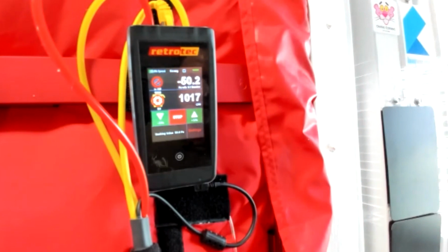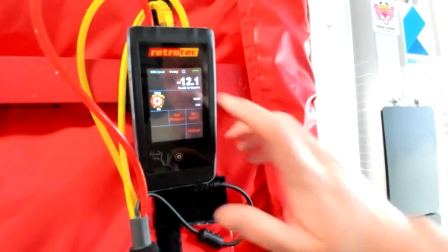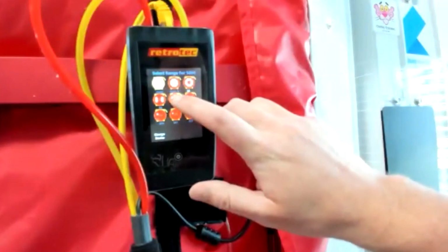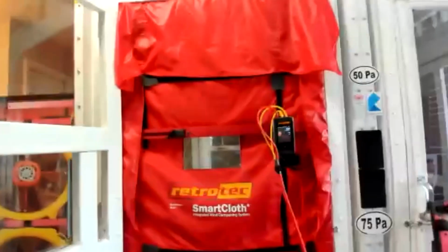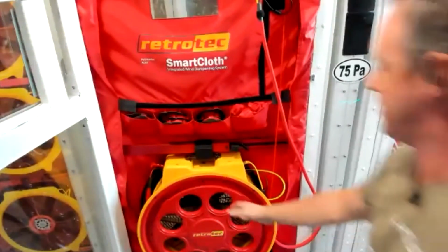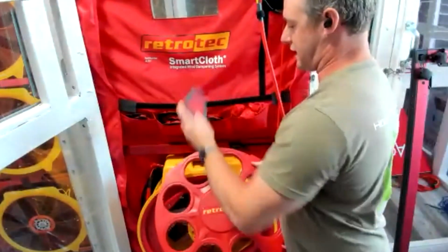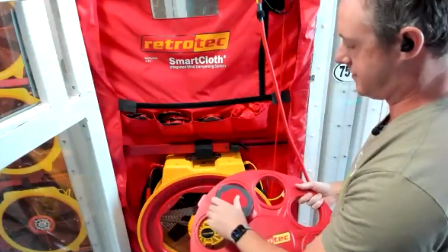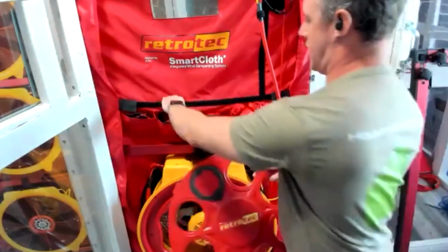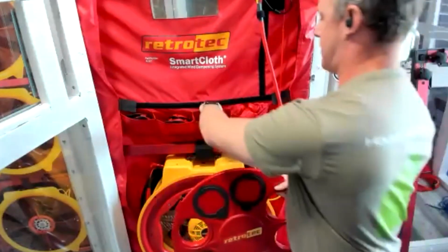Now, to demonstrate what would happen if I'm too low, we'll stop the fan again. I'm going to change the range to B2, and then on the fan, I'm going to make that match. I want to show you this because this is what happens. I want you to see what it looks like whenever you can't get to your target pressure and you need to do the opposite of what we just did. Our fan was too open before.